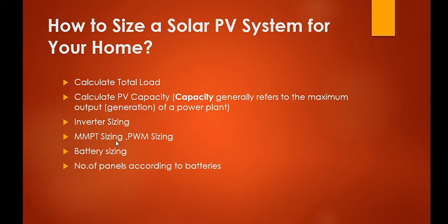The third point is inverter sizing. The fourth point is MPPT sizing and PWM sizing. These both are charge controllers. Then battery sizing, if you are using a battery grid system with storage or an off-grid system with storage, you need to follow this step. The last one is the number of panels according to batteries.